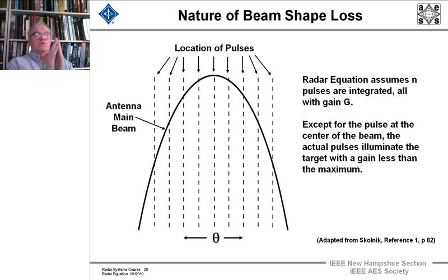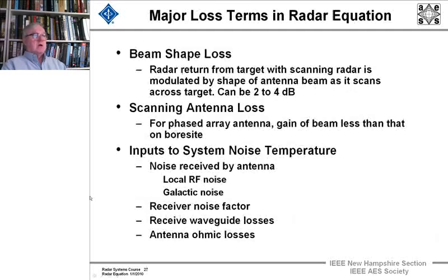And what that will do is it will do two things. It will lower the reflectivity out at the edges, but that amplitude modulation will also give rise to the ground clutter, a stationary object like that chimney, not having zero Doppler. It'll be zero main Doppler, but it will spread the Doppler return. And that will leak into the Doppler filters of your system. It's something that has to be taken into account.